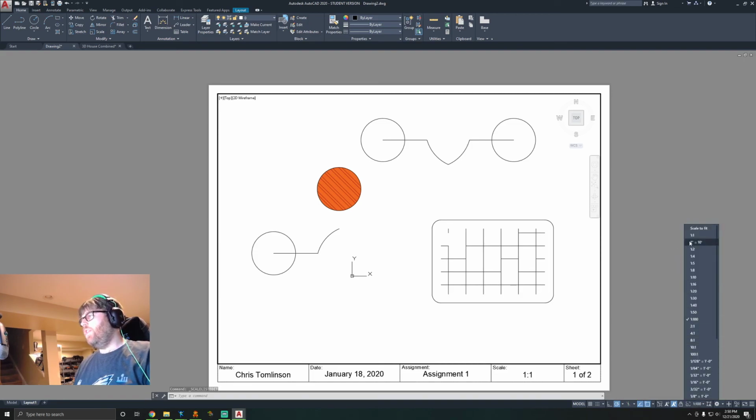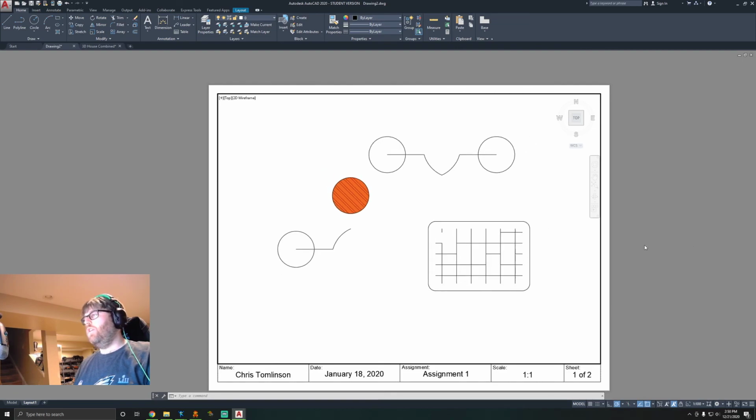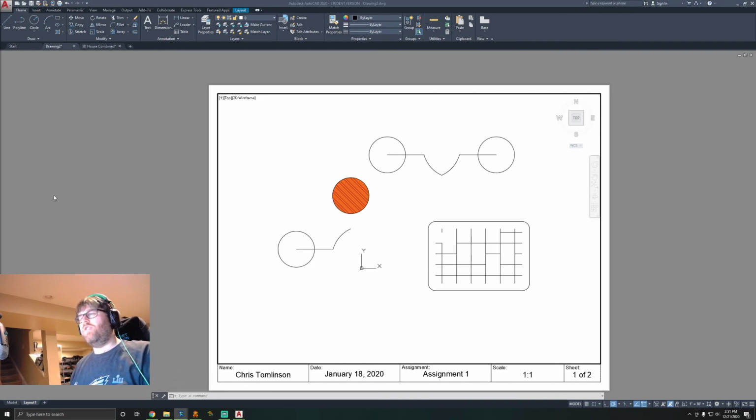It's in here. This should zoom out slightly because it's a 1 to 120 instead of a 1 to 100, and it does. It still looks pretty good. So that's how you do viewport scaling, and that is the basics of 2D drawing. There will be another presentation more focused on 3D drawings and stuff for your house, but this one I'm going to end here.